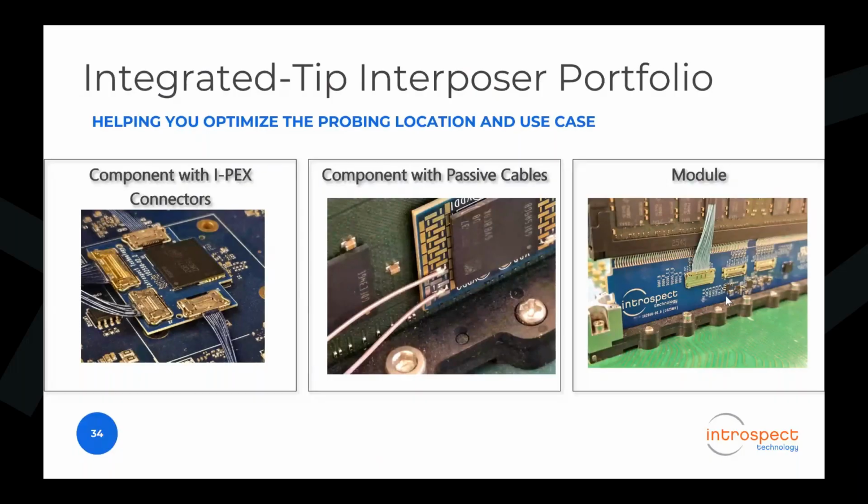instead of 0. But keep in mind that these tips are high impedance tips, right? So they're really like 1K and above impedance. So they do not load down your DDR bus. This is not a passive, just a resistor divider and that's it. This is really a high impedance tip. So the amount of loading on your DDR5 bus is very, very low. When we look at the return loss when the tip is attached versus when it's not attached, it's within only a couple of ohms away from the nominal impedance of the trace.